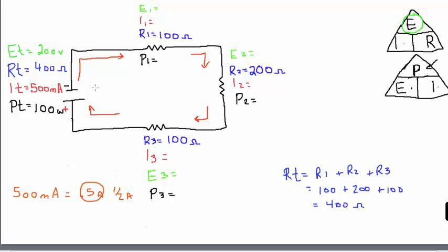All right, so we're going to follow electron current flow, and we'll follow it here. We'll start over here. Since I have a series circuit, all of the current must go through the individual resistors. All of that current must go through here, and it must go through this resistor, and it must go through this resistor here. So in series circuits, we say that the value of current through a resistor is equal to the total current in the circuit.